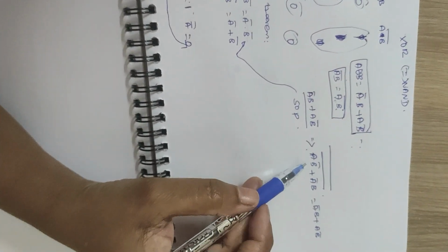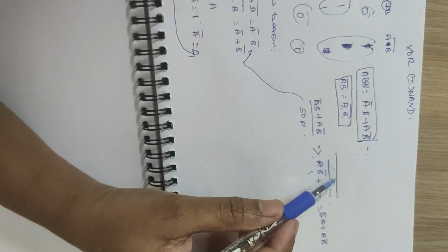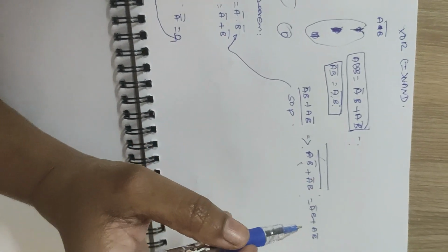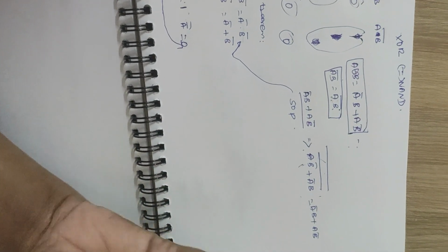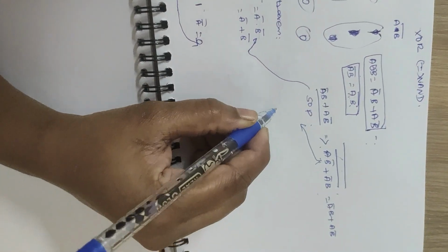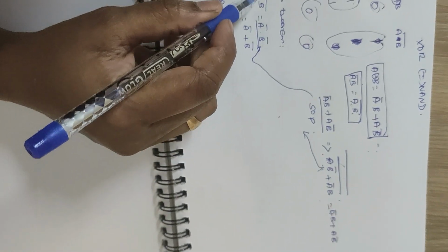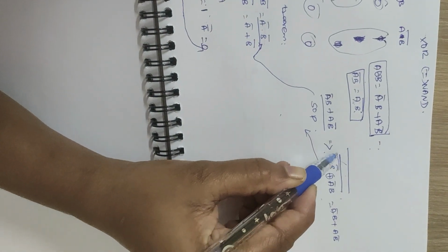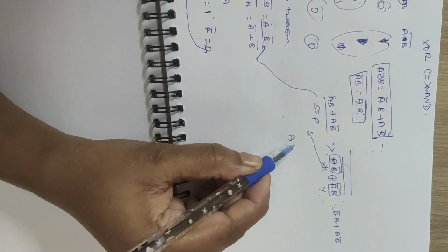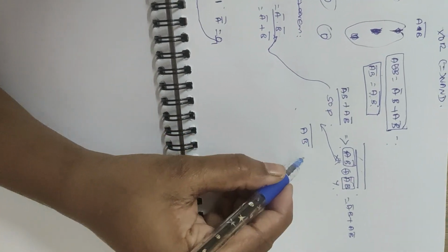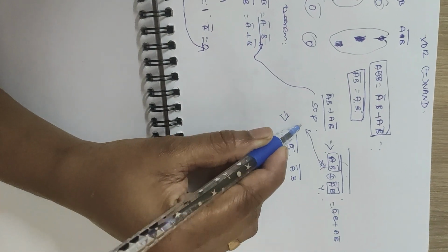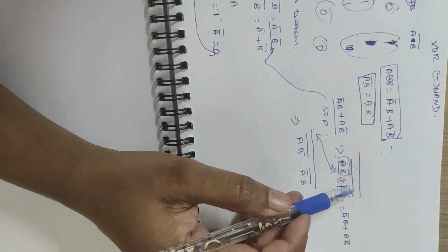So we can apply a double inversion in order to implement this using NAND gates. What De Morgan's theorem says is, if you see the OR operator here, consider one side as one input and the other as another input. Then you have the whole bar of (AB bar)bar dot (A bar B)bar, with the outer bar already there, because double inversion doesn't change the functionality.